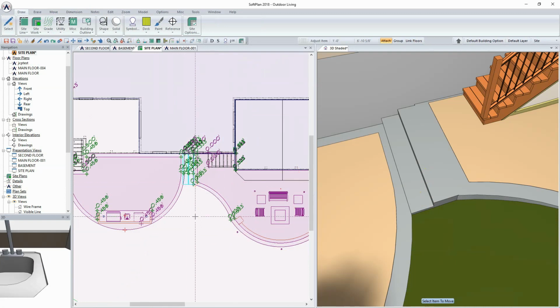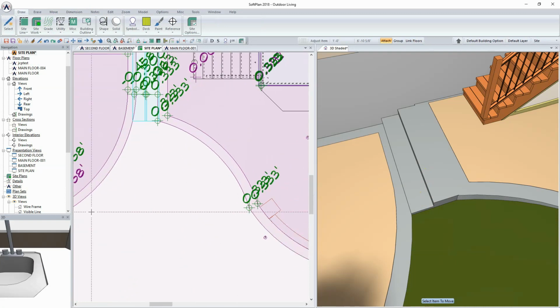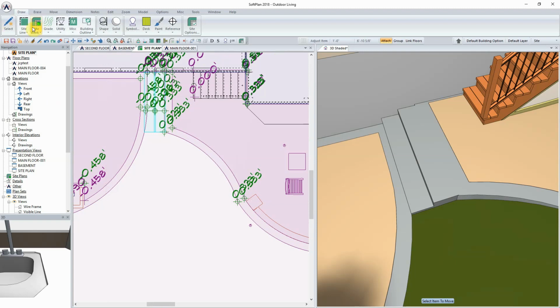and I've managed to square this area off here now, I can come in and actually begin to sketch in where I want the planting bed. And so still within site mode, and under draw, you can come into site work, and this will give you the ability to select a planting bed. Now the planting bed at this point, as I begin to sketch it in, I'll have the option of both line and spline. And I'm going to use the line and trace very angular type shapes to begin with, and then in time I'll come back and modify to set up certain lines to mimic or adhere to the same radius as the curbs that we're running this up against.